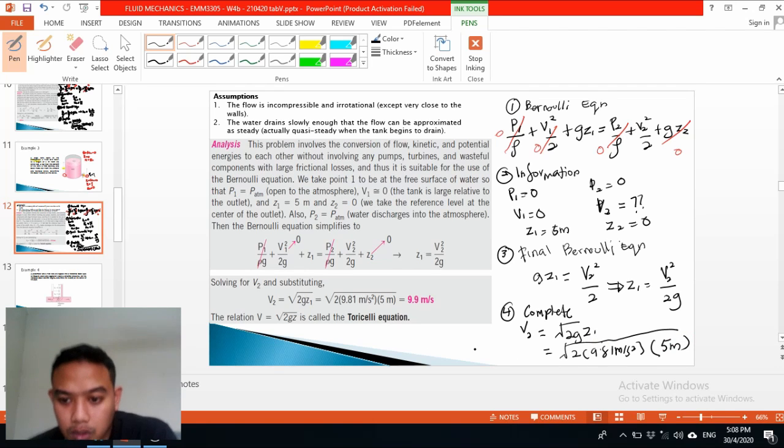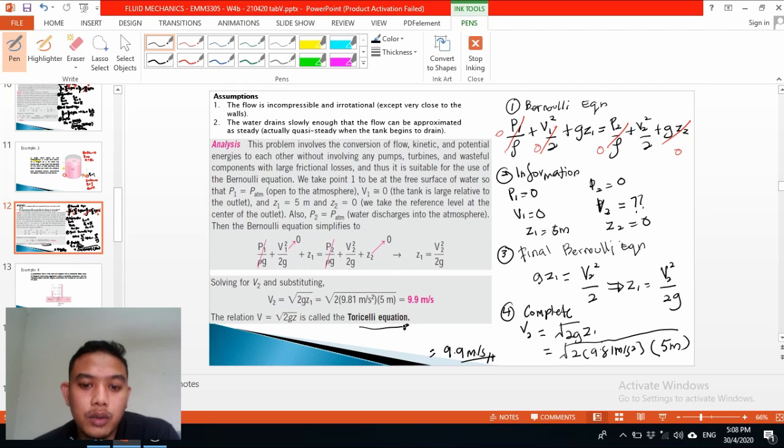So your final answer is 9.9 meter per second. V equal to square root of 2gz is also called the Torricelli equation.